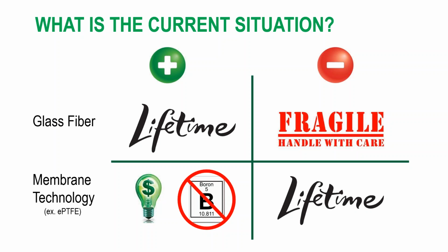But the downside, again, is lifetime, because we're looking at a media that either allows a lot of particles to pass through, or we have to layer upon layer upon layer, which creates an artificial pressure drop. And of course, it loads very quickly, compromising the filter in general.